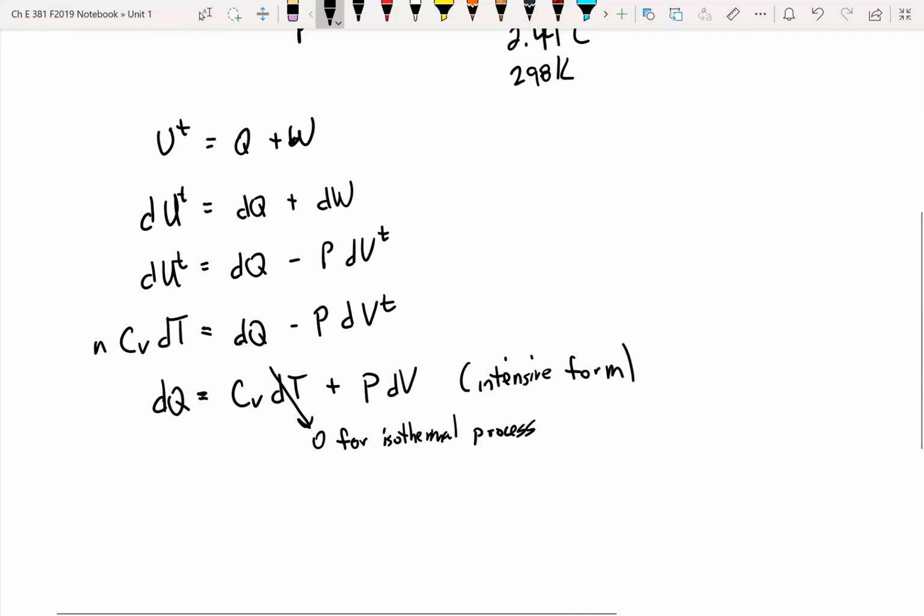It is going to start as roughly adiabatic actually over a short period of time. The temperature is going to rise, and then you're going to have a temperature gradient between the interior of the cylinder and the bath, and that temperature gradient is going to allow heat to flow out of the gas into the surroundings, returning the temperature back to roughly that constant state. So that's like an isothermal process, but it's not an isothermal process. So this isothermal process is completely in our heads.